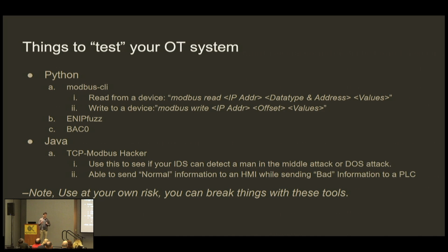Just a real quick thing. If you wanted to test your OT system for whatever reason that I can't quite fathom, you have Python and Java in order to help you do this. With Python, you have Modbus CLI, which I have an example for you there if you want to know how to use it, which will write directly to the different coils inside of a PLC.